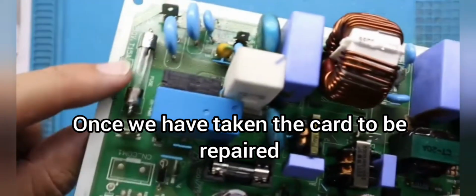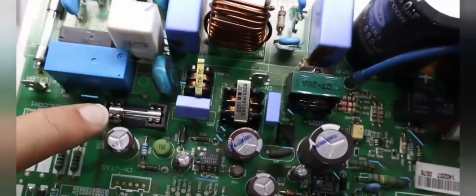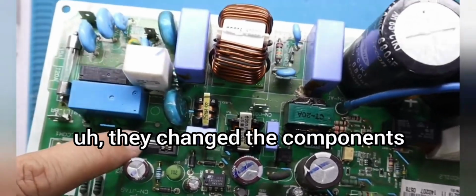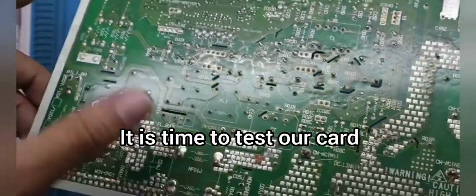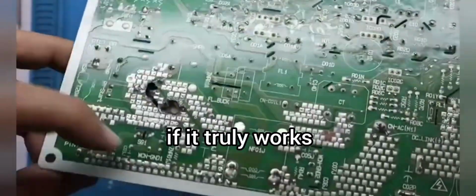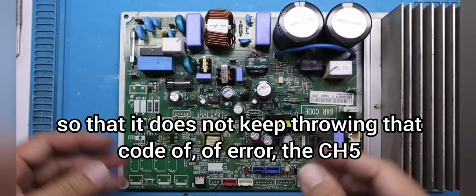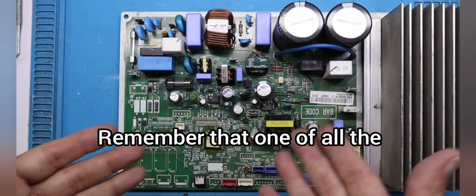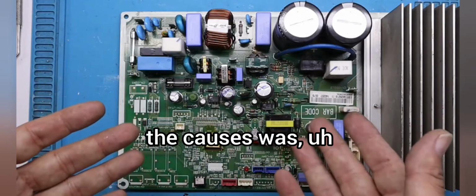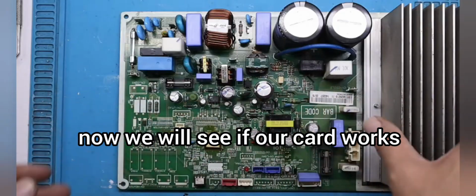Once we have taken the card to be repaired, where they changed the two fuses, they changed the components, or you have repaired it yourselves, look how it turned out. It is time to test our card, if it truly works, so that it does not keep throwing that error code, the CH05, which is the intercommunication error. Remember that one of the causes was that the card is shorted. So now we will see if our card works.